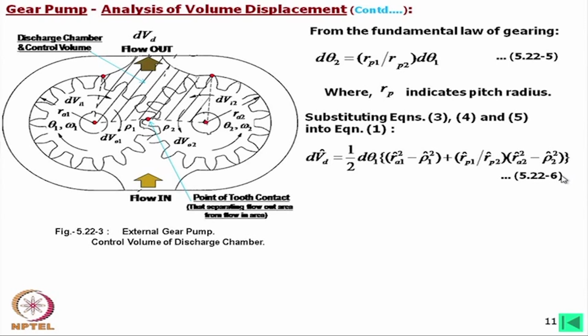So, remember the first equations and all the equations we have derived so far, we will arrive at these equations. Now, in this derivation, they have considered the pitch circle, but I prefer, or anyone can prefer, just directly the base circle. You can consider the base circle instead of the pitch circle.